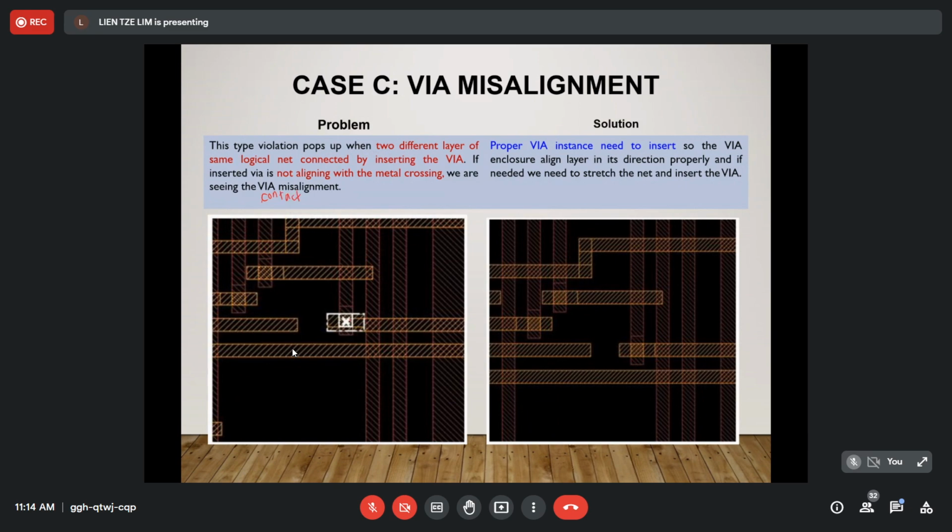This is the contact. So the contact here means this part. You see that this contact is slightly misaligned. We can realign it to make it align properly with the crossing between the two layers. After aligning it properly, it will look like this. So this is the solution. The issues shown here are just these three issues from the three examples.